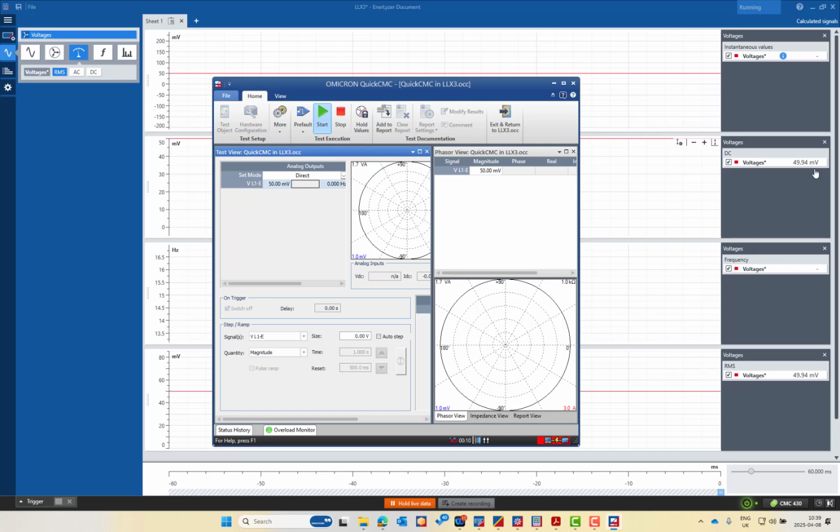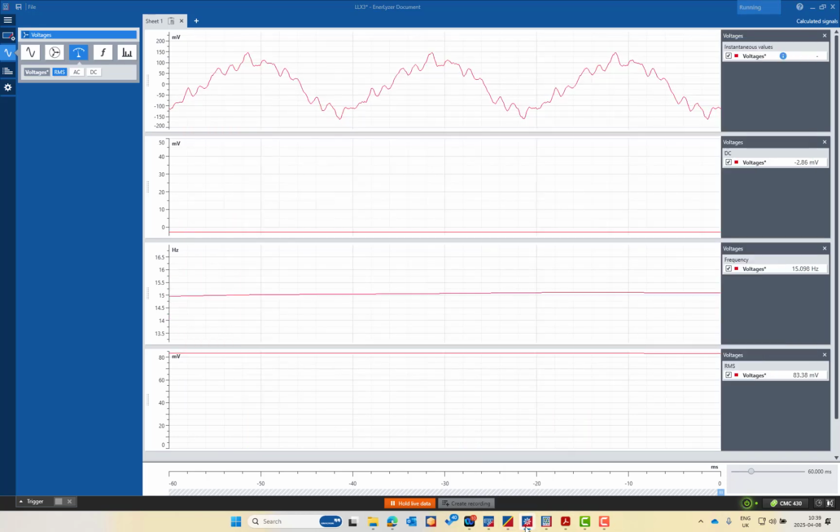This means 60 microvolt. And in that range, we have more than that in our accuracy limits. So it's accepted based on our technical specification for that range. Furthermore, if you need to adjust the accuracy to be more accurate, we have another parameter I will show you now from the hardware configuration.